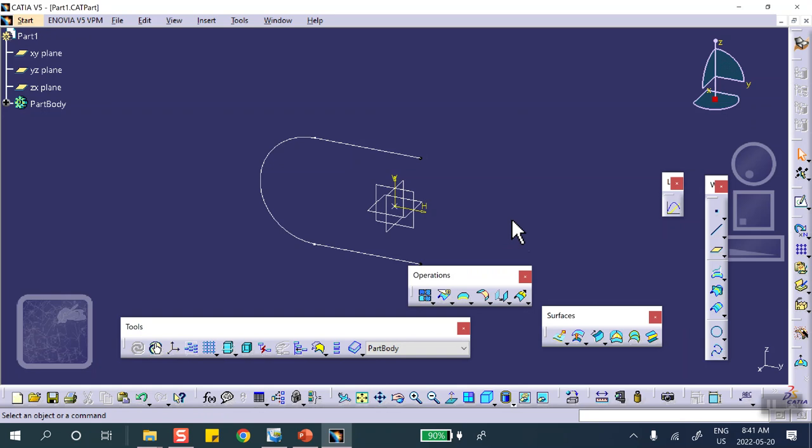The way the orientation point works is that from that point, you drop a perpendicular to the curve, for example the bottom edge, the top edge, or the circle. You drop a perpendicular. That is your y-axis. X is along the beam, and Z is perpendicular to both of them. Knowing this removes the uncertainty and randomness out of it. In this case, the only restriction is that this point cannot be on this curve or on the continuation of it. Because if you drop a perpendicular from that point to the curve that it sits on, you're going to have a problem. That's the only restriction. Exit.